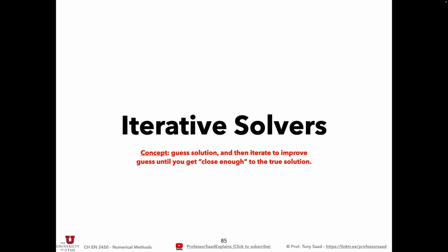So we've already started doing approximations. This heat transfer equation is an approximation to reality. So why do I need to solve that approximation exactly? Why not solve it approximately? And that's the idea of iterative solvers. We start with a guess for the solution. How do you start with the guess? I don't know. Maybe we take the average temperature for this problem. If the rod is at 500 and 300, maybe the average temperature is going to be 400. So we're going to guess that the solution is 400, and it's going to converge to the correct solution. It's going to be just fine.